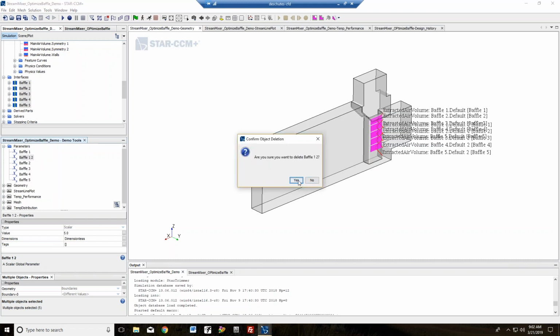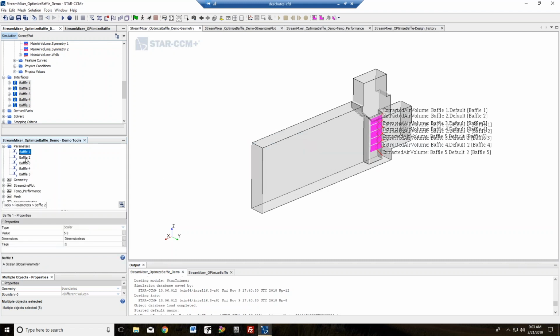That's shown right here. So we've parameterized these resistances, and there's many resources out there. We've used Idelchik and Fried in the past that give you hand calculations for associating resistances with certain densities of a screen mesh or a pattern of holes. So there's engineering justification for kind of going back to a simplified model such as this.